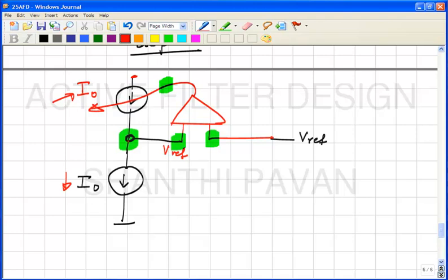So this current is now dependent on this current, and it's always equal to I naught. One could also conceive of the opposite situation where the push-up current is fixed and the lower current source is controlled, and it's controlled based on the potential at the junction of those two current sources. Does it make sense?